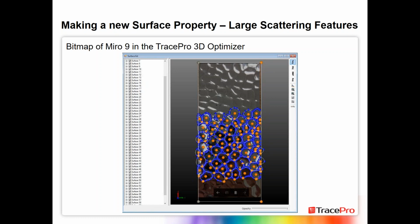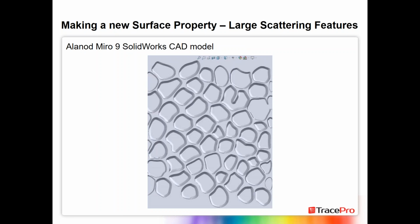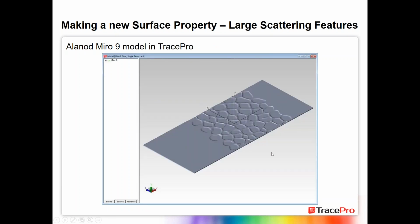So what I did is I took that model, I opened it up in SolidWorks. I imported it as an SAT file, I believe. And then in SolidWorks, I added radiuses to the edges, both the top and bottom edges of all these features, or dimples as I like to call them. So now we have a better representation of what the actual surface looked like. So from there, I then exported the model from SolidWorks and opened it here in TracePro.